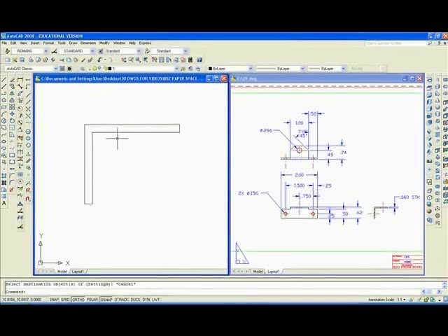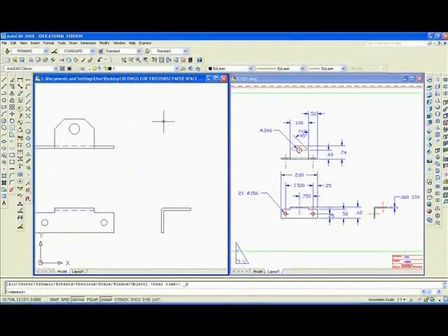When you bend sheet metal like this, it's so thin, you can have a sharp corner on the inside, but the outside corner is going to have a radius, which will be the thickness of the material. So I'll type F, enter, R, enter, and the thickness is 0.06. So we'll have an outside radius of 0.06. And I'll zoom previous.